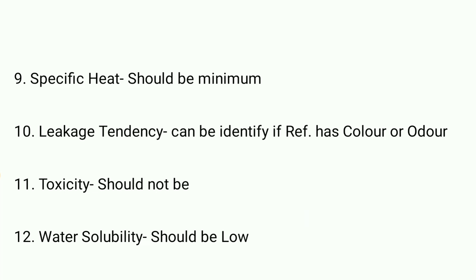Refrigerant should not have a leakage tendency mostly, but if it does, the refrigerant should have some color or odor, so that we can detect that there is a leakage. Toxicity should not be there, because if there is toxicity, it will be a problem for humans. And water solubility should be low. If it is higher, then corrosion takes place in various components. So these are the basic combination of properties of any desired refrigerant.